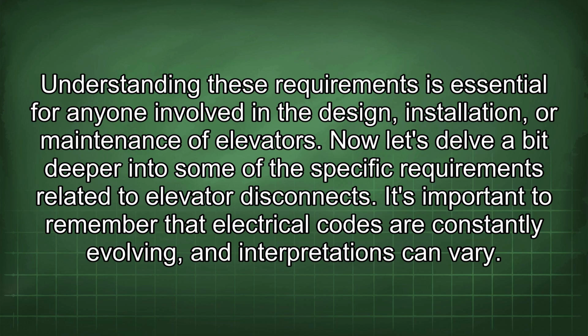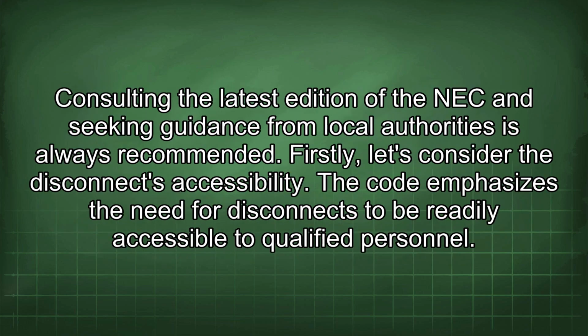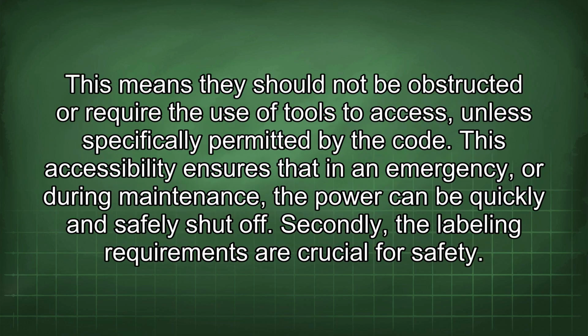Now let's delve a bit deeper into some of the specific requirements related to elevator disconnects. It's important to remember that electrical codes are constantly evolving and interpretations can vary. Consulting the latest edition of the NEC and seeking guidance from local authorities is always recommended. Firstly, let's consider the disconnect's accessibility. The code emphasizes the need for disconnects to be readily accessible to qualified personnel. This means they should not be obstructed or require the use of tools to access, unless specifically permitted by the code. This accessibility ensures that in an emergency or during maintenance the power can be quickly and safely shut off.